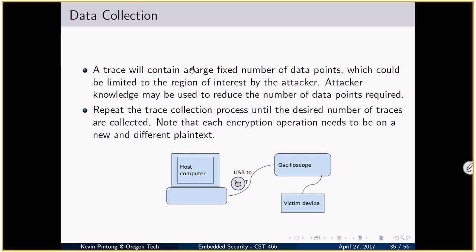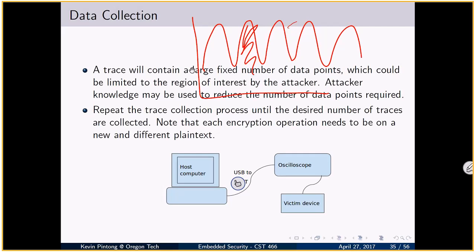What I'm saying by that statement is this. We had all this data, but the truth of the matter is you can zoom in on one particular point. There could be 1 to 10 or however many points, but if you could find that single point where that XOR store operation is running for that algorithm, or that substitution step in the case of AES, and you only capture this one spot, you can actually figure out the key without capturing any of this over here.